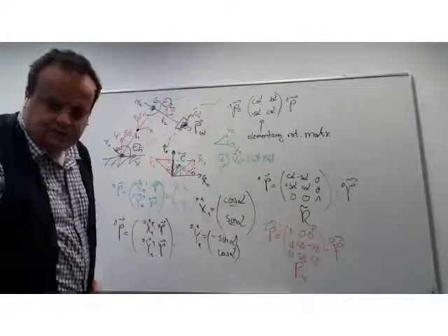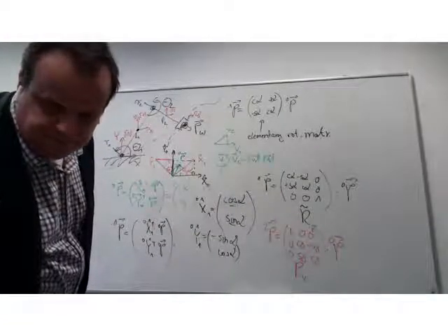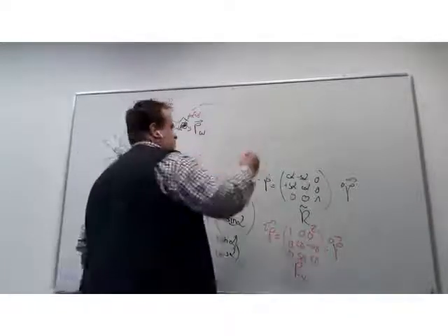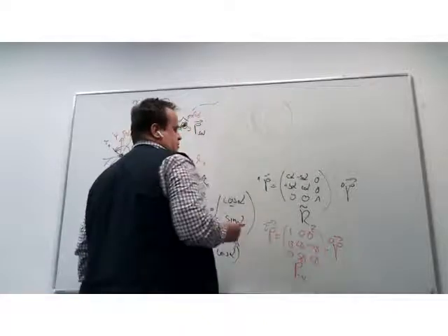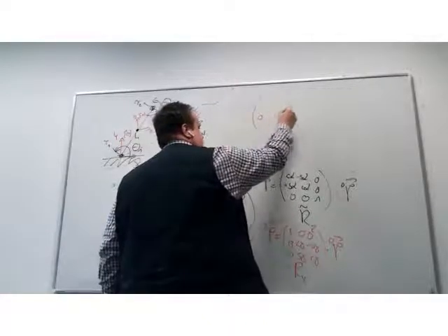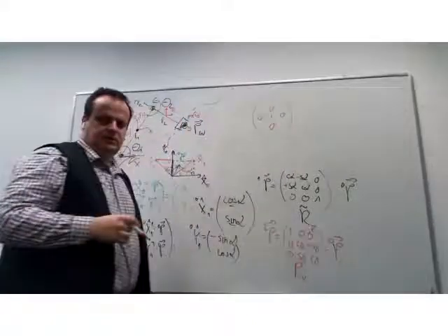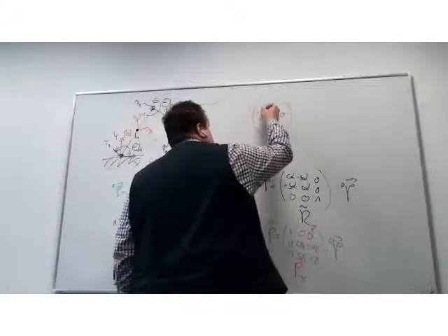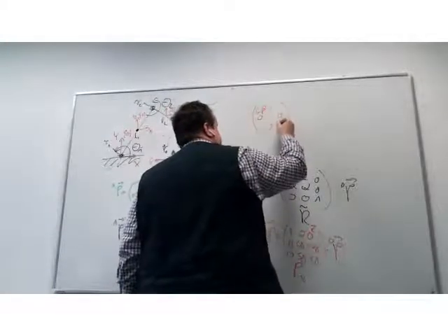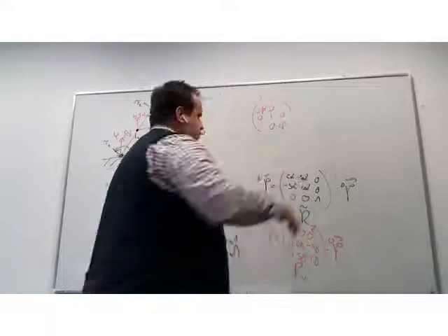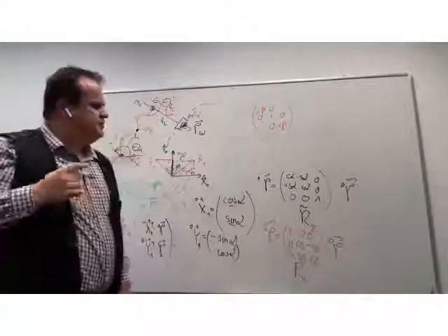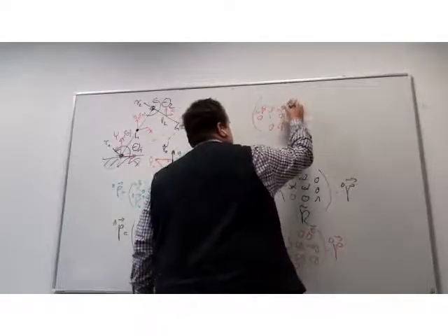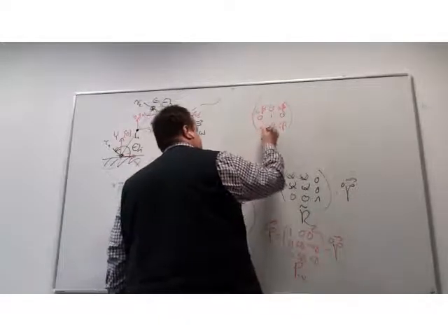And the last one, give me a second. The last elementary rotation matrix would be, of course, rotating around y. So the y coordinate stays preserved. Here I have also the cosine beta in the diagonal. For the y, you need to remember that the sign changes. So the y coordinate has a plus sine beta here and minus sine beta here.